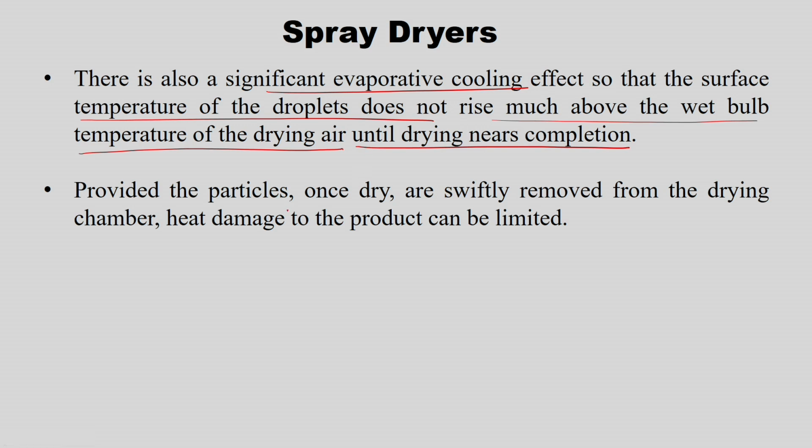And provided the particles once dry are swiftly removed from the drying chamber, heat damage to the product can be limited. So that is another advantage of the spray dryer. One advantage is that due to the significant evaporative cooling effect, your droplet temperature does not rise and is always less than the wet bulb temperature of the drying air throughout the drying period. The second advantage is that the products are swiftly removed from the drying chamber, so that the heat damage to the product is very limited. So for example, this is your drying chamber.